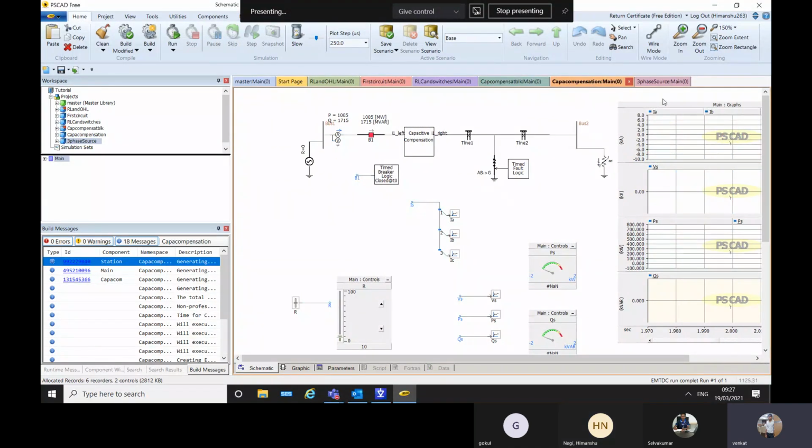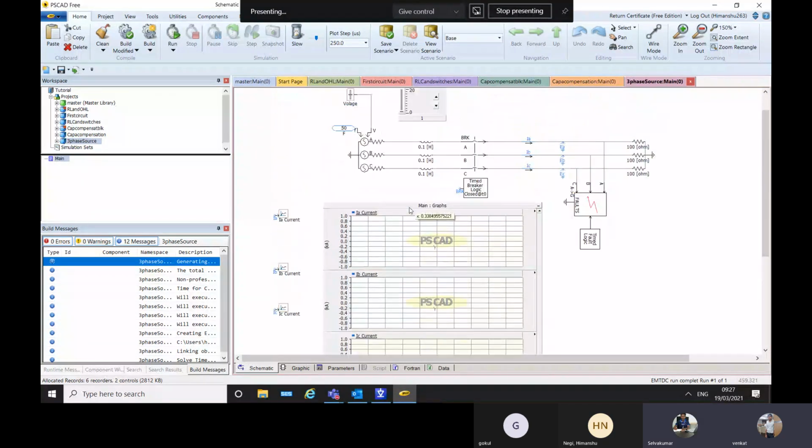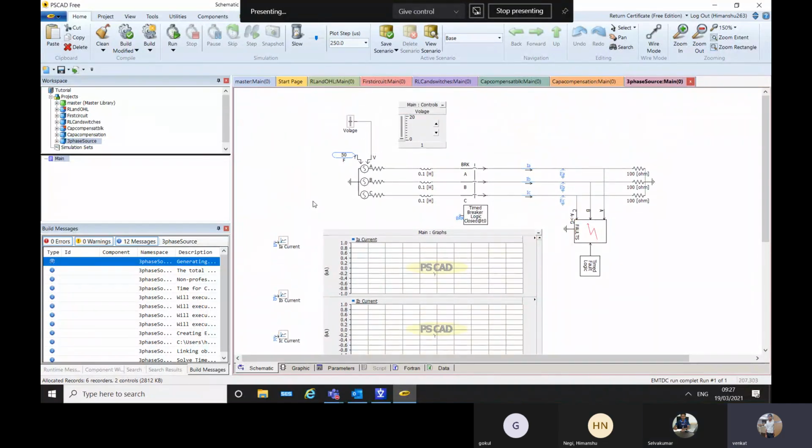Then we can start with modeling of sources itself, sir. That's how we used to model the real-time source, and how we tried to match the fault current levels, and from there we used to start the modeling. But one thing you need to understand: he is not moving from power system studies to insulation coordination. In power system studies, when you go to source modeling, you need the short circuit level and the X by R ratio, which we get from a short circuit report itself.